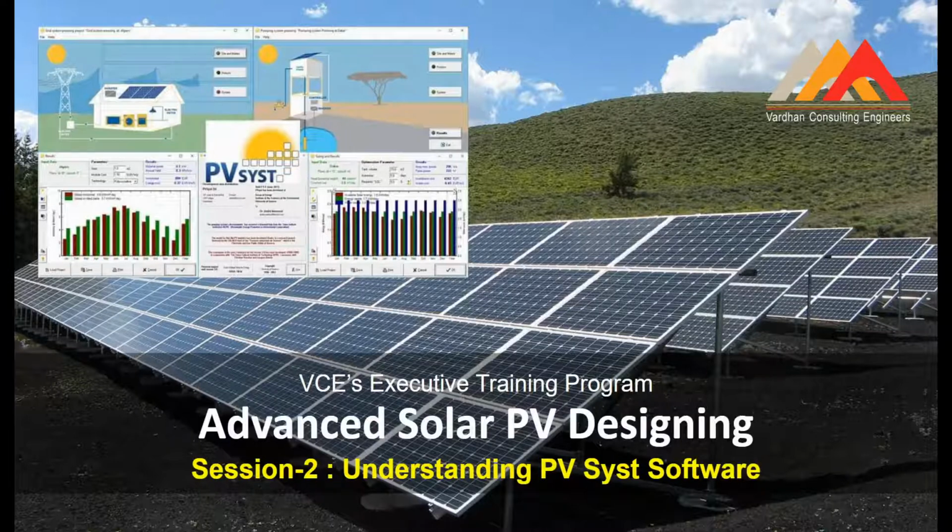Let's say for a 5 megawatt plant, you want only 5 inverters, that's it. But string inverters are more effective because they are small, easy to install, easy to maintain. So which string inverter you want to use, you can choose from the list, 50, 60, 100 kilowatt, 250 kilowatt, up to you.